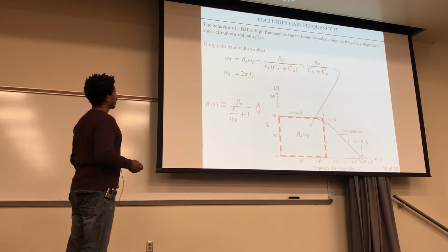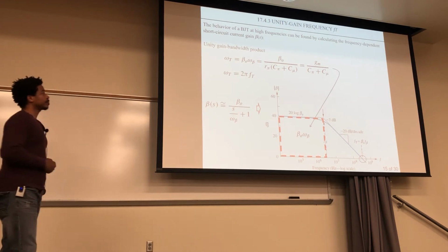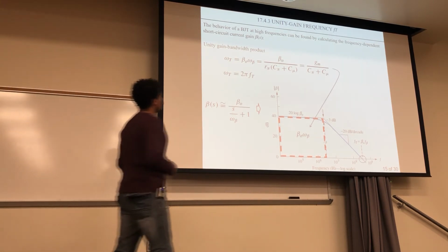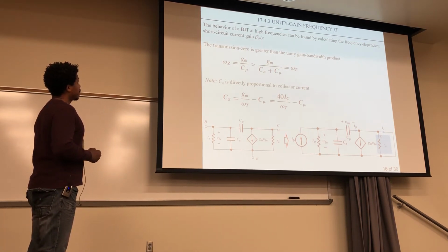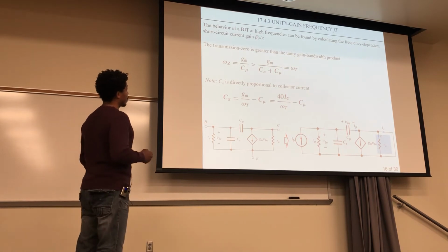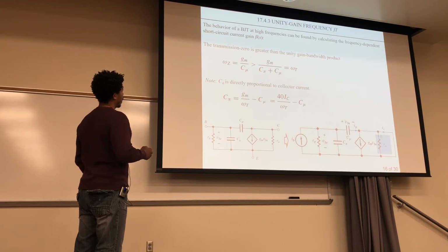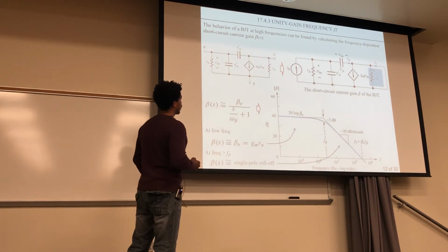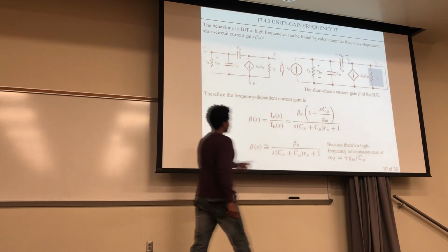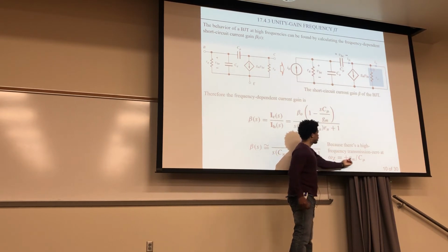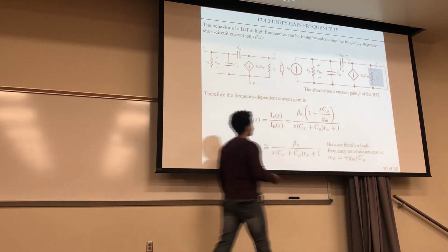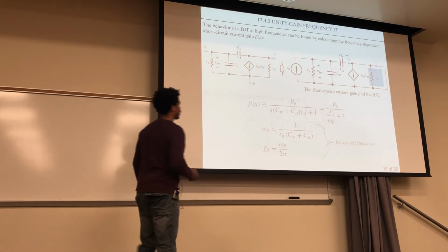All right, so the transmission zero is actually greater than unity gain, because we said it was pretty far out there. So that's what this expression was, right? And remember what that was. That was to create a zero here, right? So when s became this, omega m over C mu, then this expression goes to 0, okay? So that's what that is. And that's greater than this frequency of omega T right here. Okay, so we're talking like way out there.